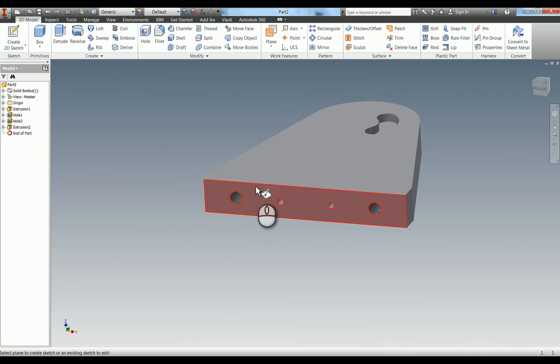There's also a hole on that face there, and be very careful which face you choose here. The drawing is telling you it's 5mm deep, and if you look at the hidden view you can see that this hole does not break through the other hole. Now if you sketch and do the hole starting on this face at 5mm deep, it will actually break through the hole. So it's very important that you look at all the views to understand exactly what's going on.